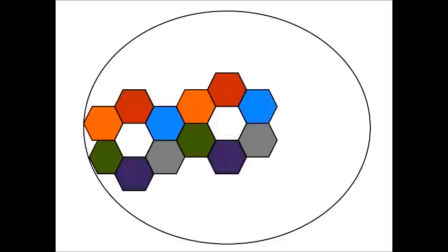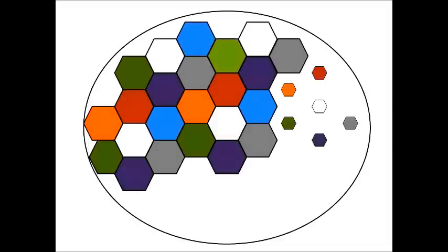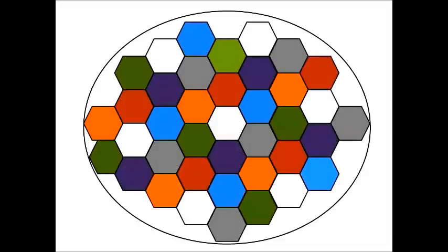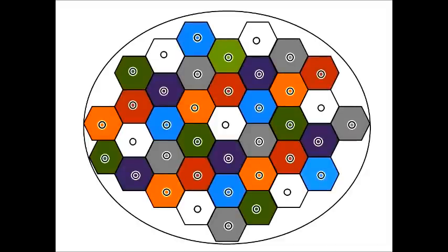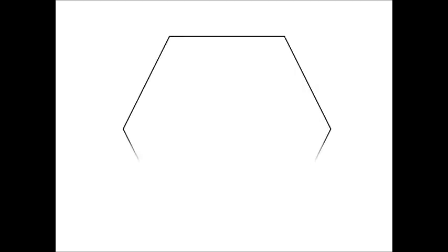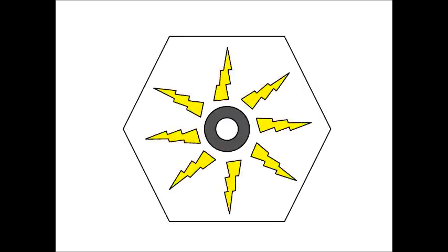Now, what is a cellular system? Consider one city. In the cellular phone system, the city is divided into smaller sections or cells. Each cell contains its own antenna and uses only a subset of all the channels. Each antenna is lower in height and emits a much weaker signal so that the same subset of channels can be used in a cell somewhere else within the city. For example, within a typical cellular system, every seventh cell uses the same set of channels.